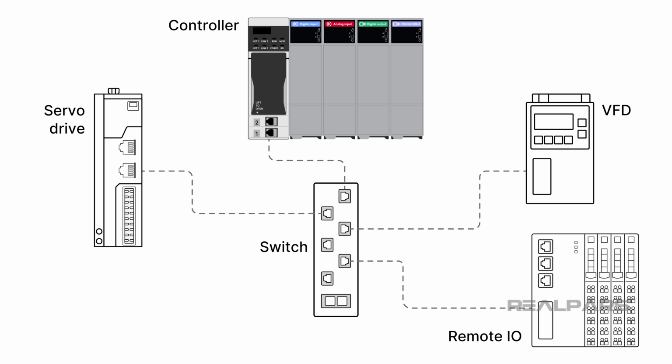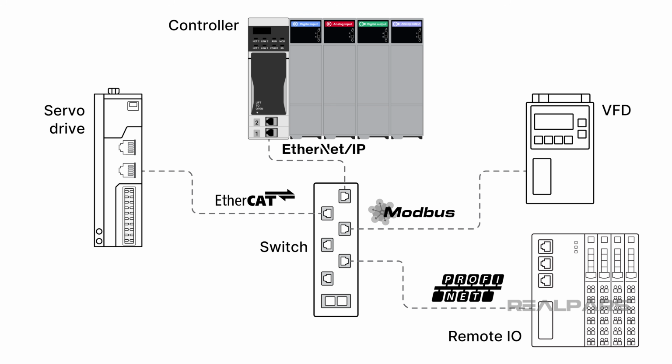An industrial network is a group of devices that are linked together to share data. Most common industrial networks use Ethernet cables and network switches to connect devices. Once they are connected together on an industrial network, devices use a communication protocol to exchange data. A communication protocol is simply a set of rules that defines how communication between devices should work. Common communication protocols include Modbus TCP/IP, Ethernet IP, and Profinet.